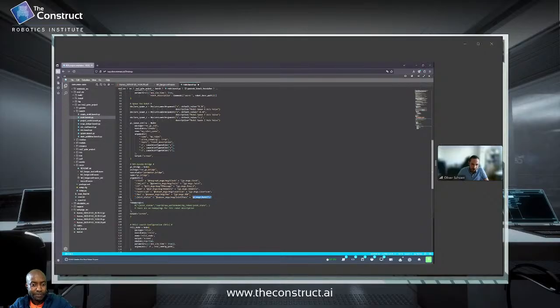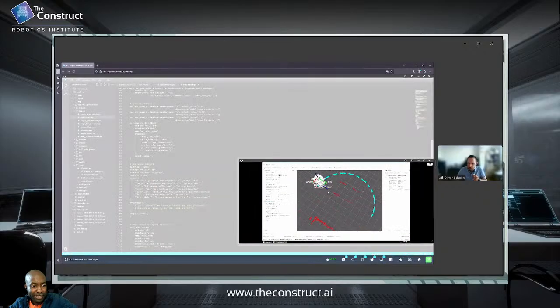So this is the direction. Oh no, I changed it. Oops. Yeah. From Gazebo to the ROS2. And I need the joint states in order to properly visualize, right? If I don't have the joint states, my wheels in the bottom here would kind of be lost. They wouldn't know in which state they are, because with the robot description, I only once get the information of my Xacro file, how the robot is set up generally, but I don't get the dynamic information when it's moving around.